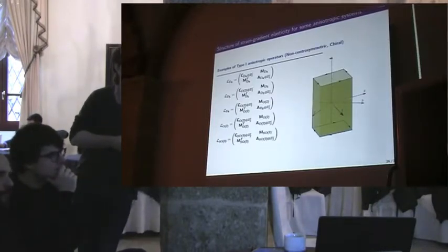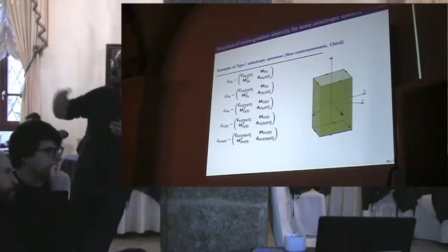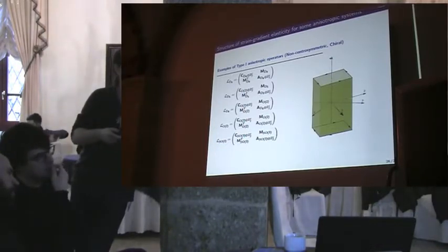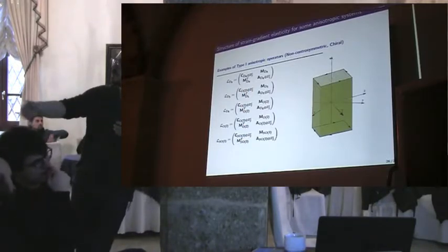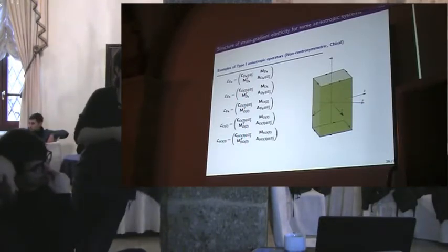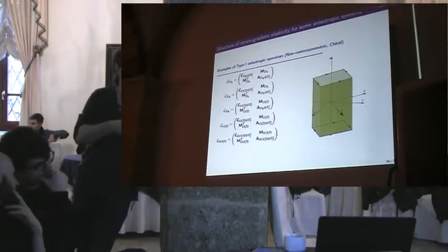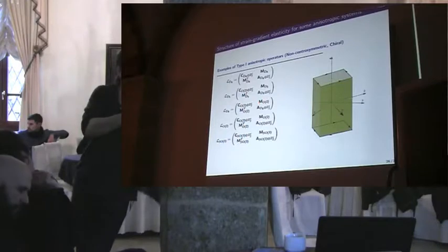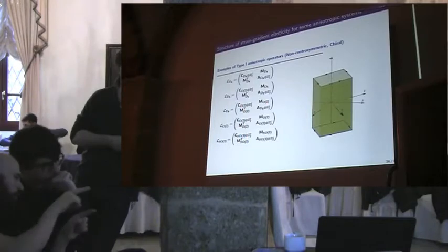And in the same paper, we provide at the end the way you can combine the different results you can have in the literature to, in each case, put those pieces together in a way that is compatible with the material symmetry you study. If you are interested in a material having this kind of material symmetry, the associated operator will be constituted of an elasticity tensor having this elementary symmetry, a coupling tensor having this elementary symmetry, and a sixth order tensor having this elementary symmetry.